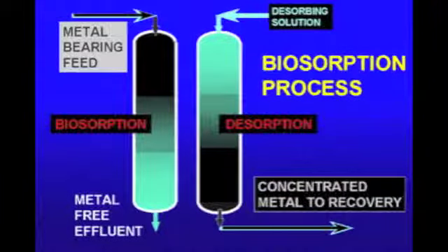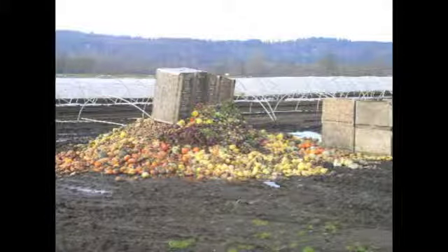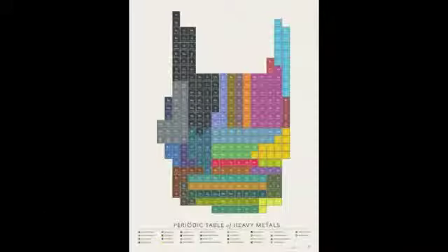Biosorption of heavy metals is the binding and concentration of adsorbents from aqueous solutions by certain types of inactive dead microbial biomass. This is done by utilizing the functional groups present in the biomass that have an affinity for heavy metal ions in order to form metal complexes or chelates. The advantages of this method include low cost, high efficiency, minimization of sludge, regeneration of biosorbents, and the possibility of metal recovery.